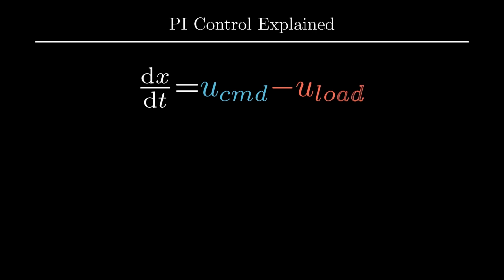First, we derive the load estimator out of first principles, detailing the specific choices a PI controller makes in its implementation. We'll show how these choices amount to an integral action. Later on, we'll discuss other choices for the estimator design, each of them yielding different variations on the standard PI controller design. Again, the starting point is the equation that models the open-loop behavior, an integrator driven by the controller's command and burdened by a load.